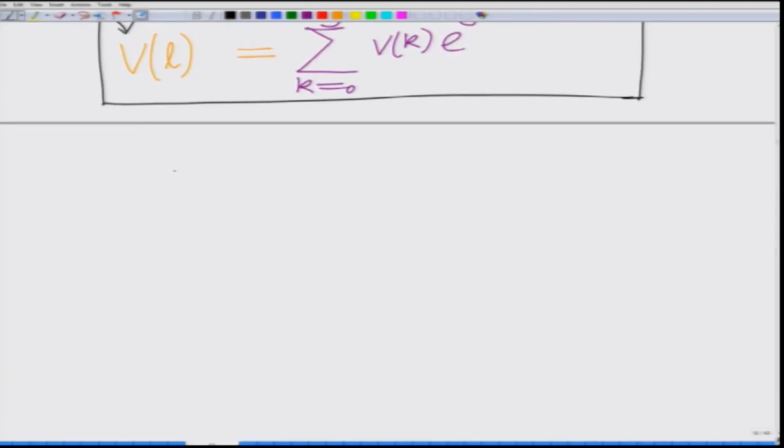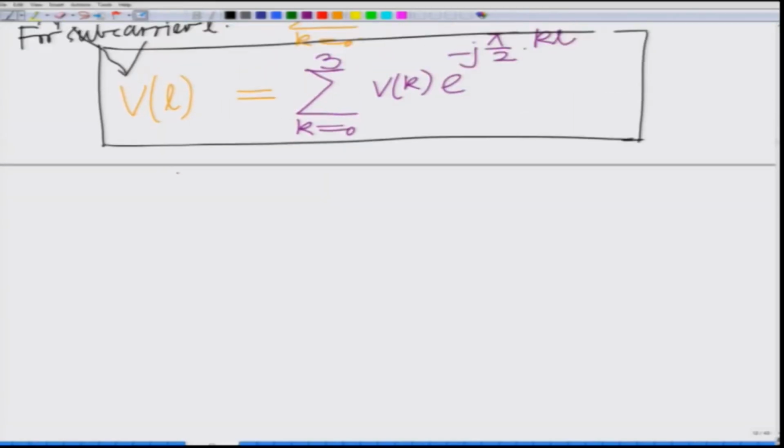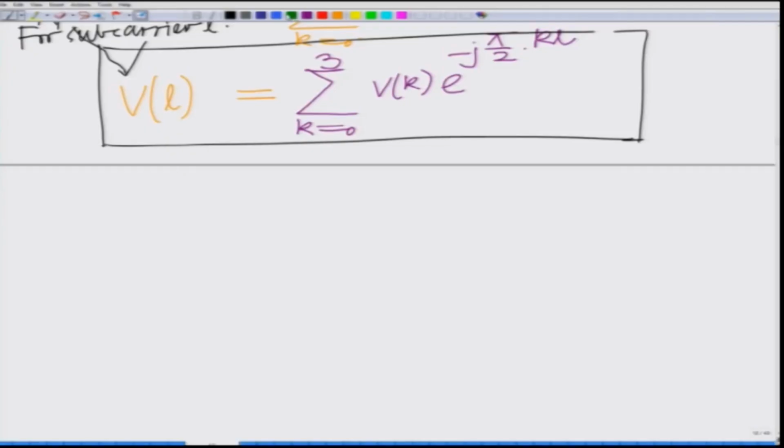And therefore, now you have the frequency domain. Remember, in the frequency domain, we have the FFT of the output y is equal to the FFT of the channel h times the FFT of the samples x, which are the symbols loaded onto the subcarriers, plus the FFT of the noise sample across each subcarrier. Rewriting it, I have FFT of y equals FFT of the channel filter h, product.